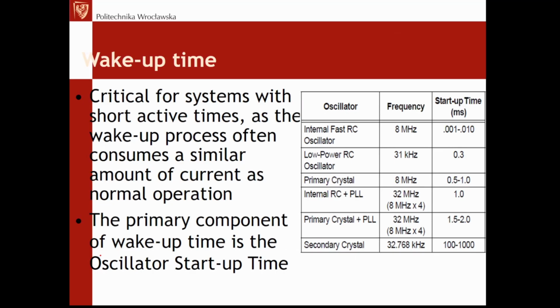But the question is not about how often the system is to be woken up, but what's the ratio between the wake-up time and the operating time. Even if we wake up the system every week, if it is to make a measurement for 1 millisecond, then having an oscillator with a startup time of 100 plus milliseconds, you must admit that it has absolutely no sense.